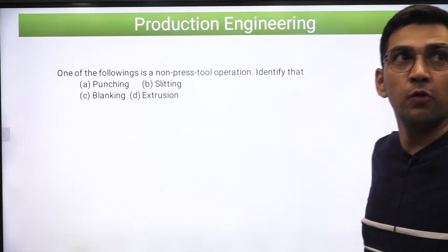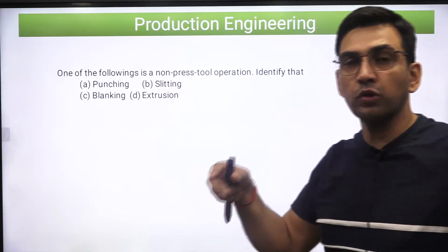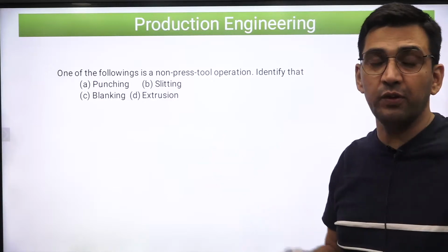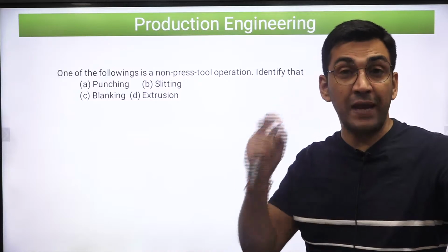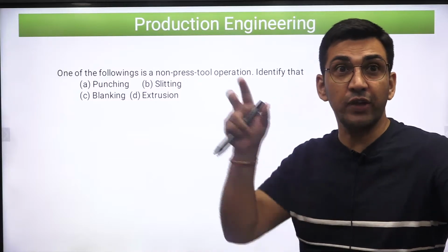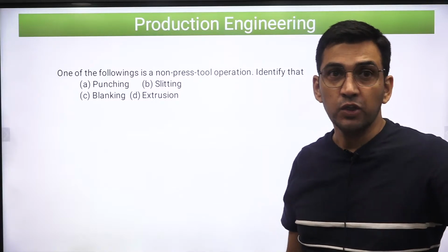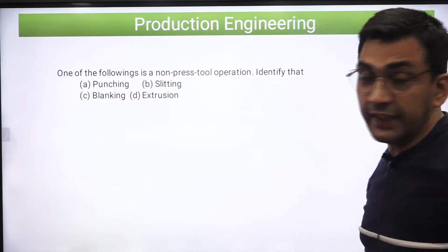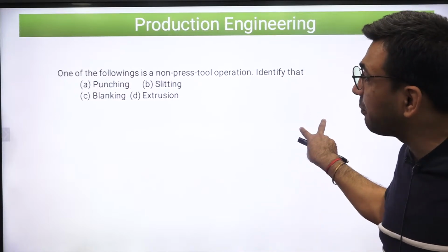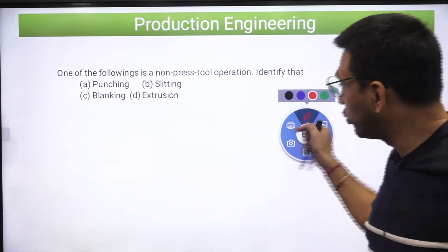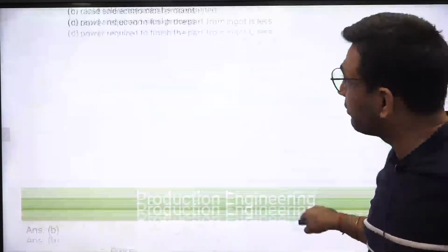Now, the point is, what is a press? For a particular machine, whether it is a deep drawing process, a blanking, or a punching operation, we are using a machine which applies the force, right? That machine we call a press. So whether it is blanking, punching, or even extrusion, in extrusion also I can make use of that machine to apply the force.